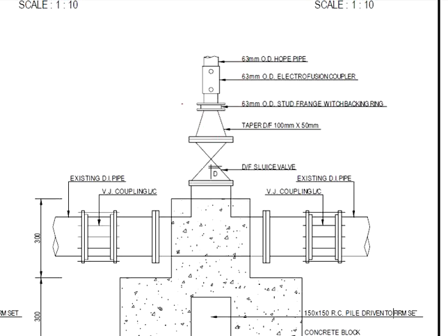You will need a taper fitting here, because the T-joint here ends up to be 100 mm diameter. This is connected with the sluice valve, also 100 mm diameter. The 100 mm diameter sluice valve cannot be directly connected to the 63 mm diameter pipe.